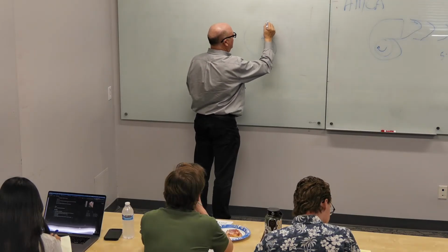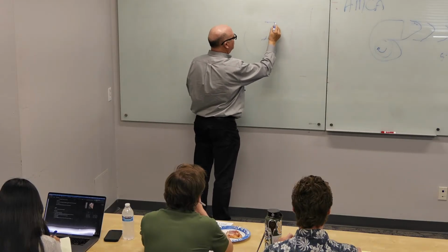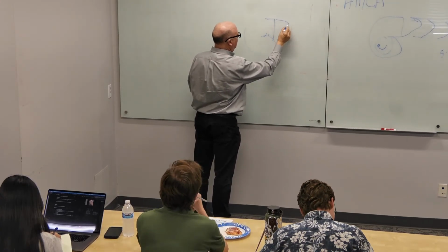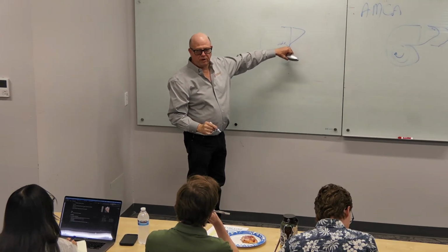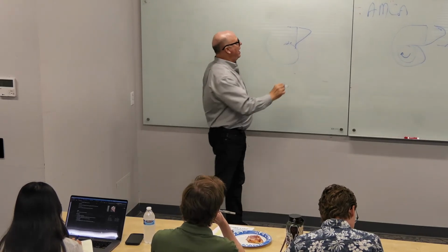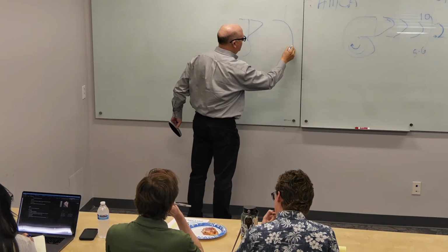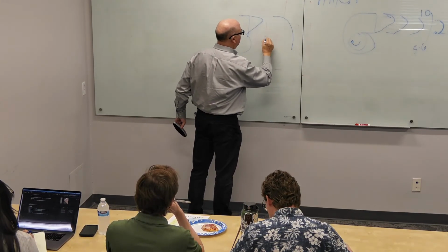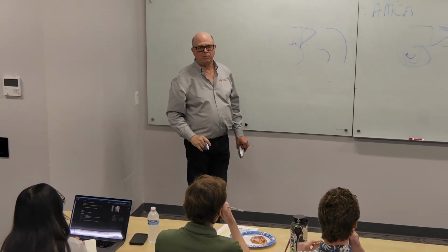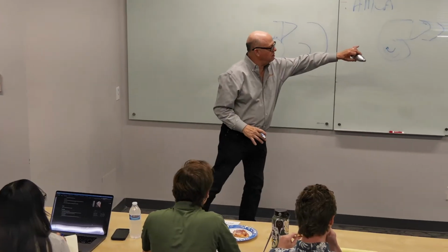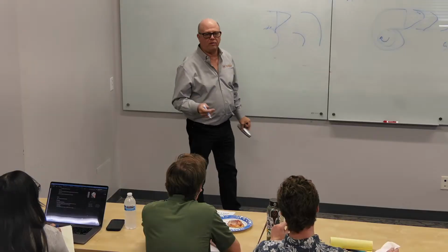And remember, we're coming off with a velocity real high up here, down to almost nothing down here at the inside edge of the duct, okay? What happens if I put a rounded fitting here real close? Well, it certainly puts a resistance on it that you're going to have to correct on the fan curve.